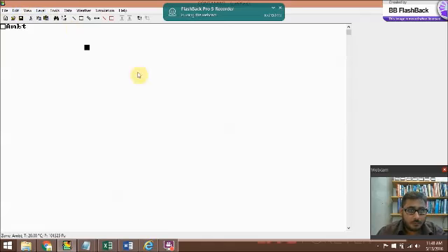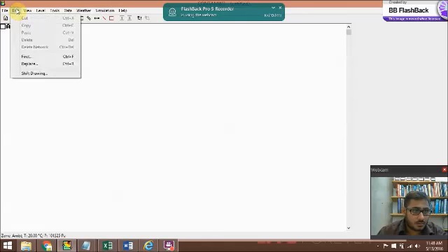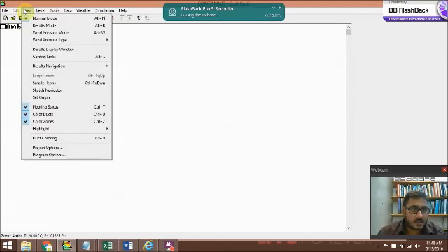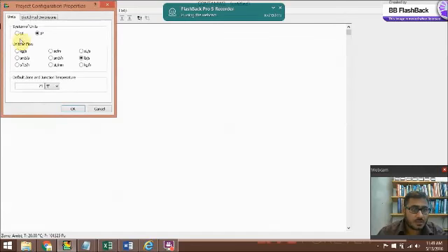Before we start our project, we would have to set what kind of units we require. To set the units, you have to go to View and Project Options. This would determine if you want SI or IP units, and your default zone temperature. So this would be your set point temperature and your units of flow.